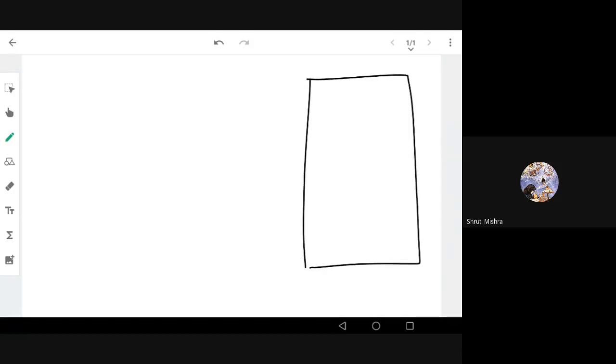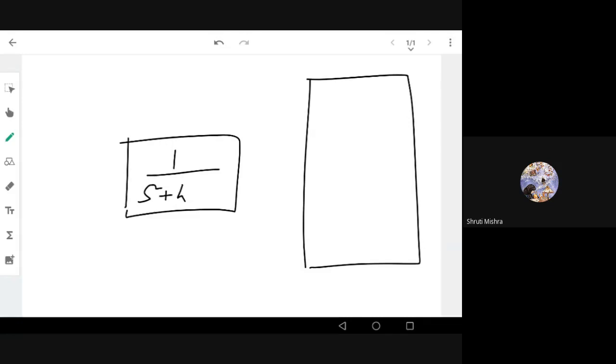All this. So you can take an example. You can take a simple transfer function, any transfer function. So there's one transfer function. For example, you can put any value like this: s square plus 4s plus 4, something like this. This is a plant. So this is the transfer function block in the Simulink model.